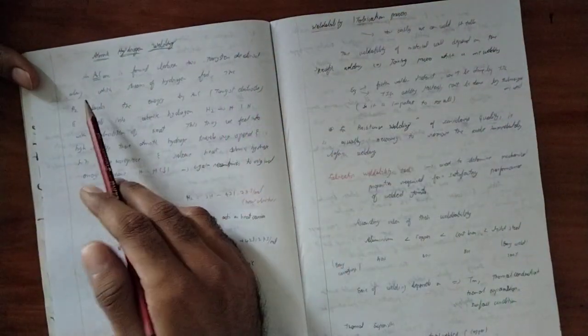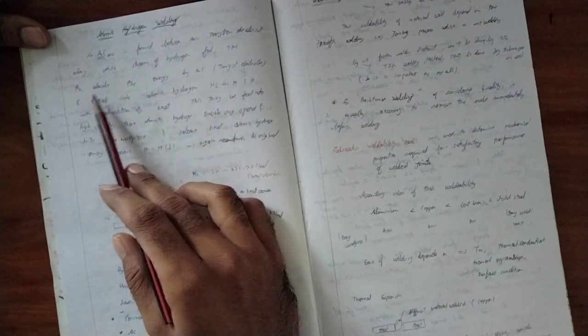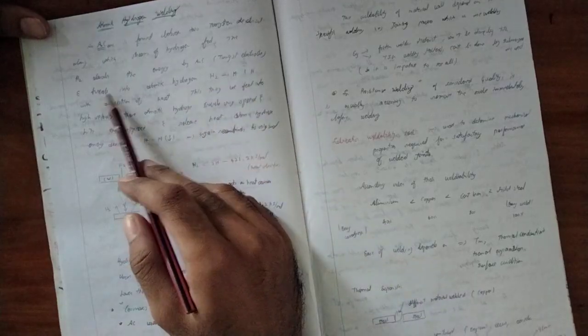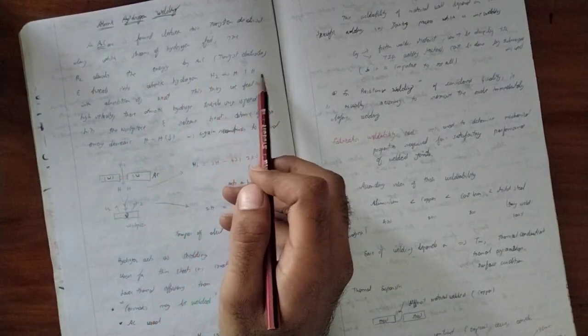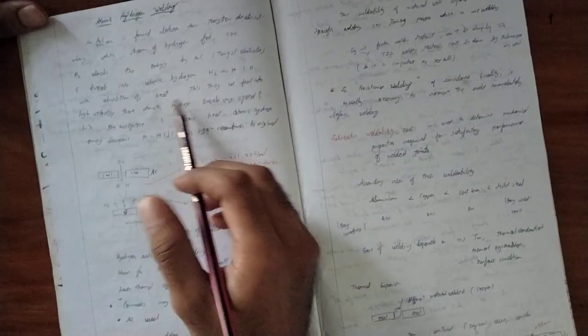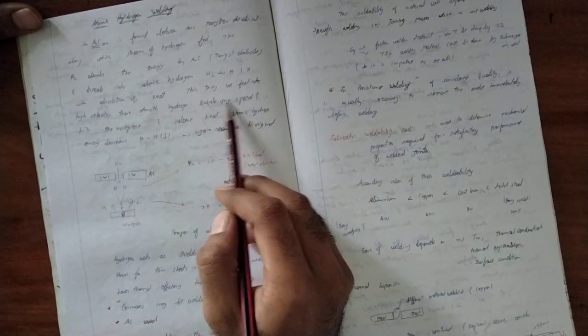In atomic hydrogen welding, you can see an AC arc is formed between two tungsten electrodes along with a stream of hydrogen feed. The hydrogen absorbs the energy from the AC arc, alternating current between the tungsten electrodes, and breaks down into atomic hydrogen. H2 becomes H and H. This we feed at high velocity, and this atomic hydrogen travels at very high speed